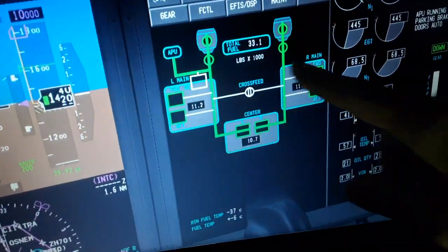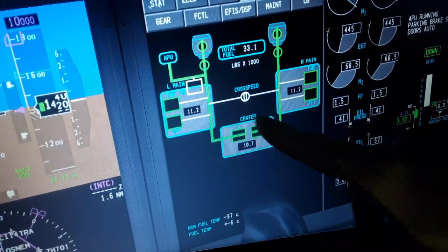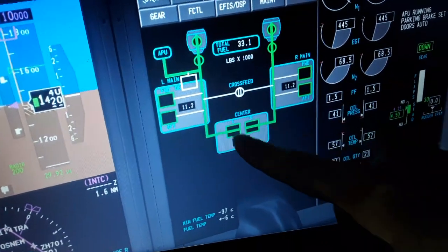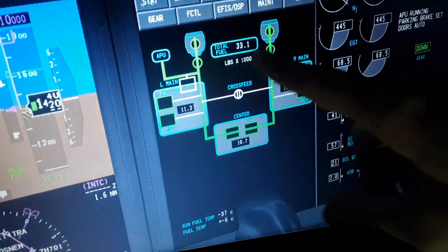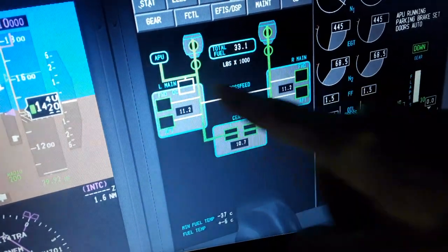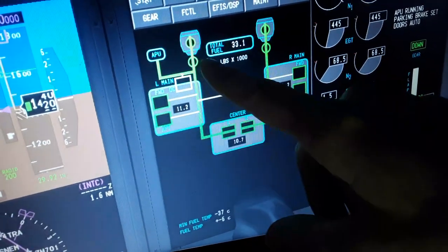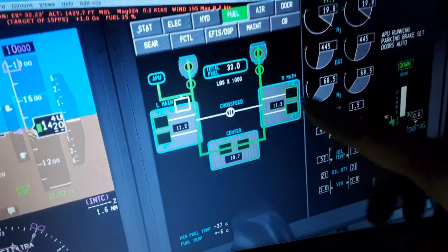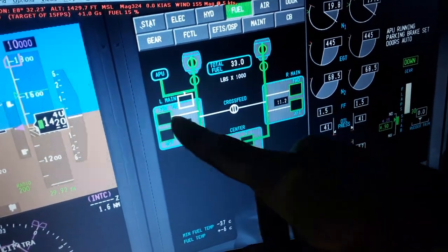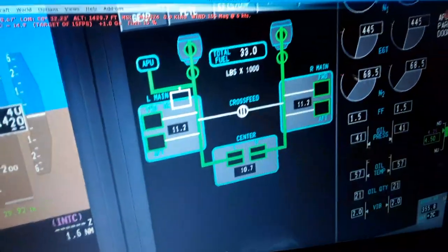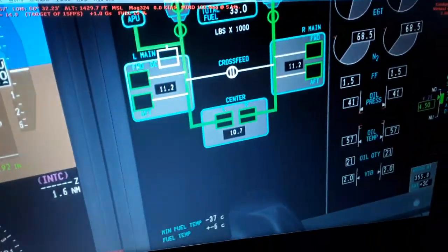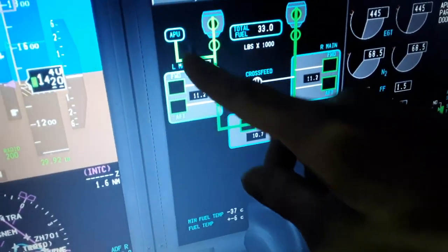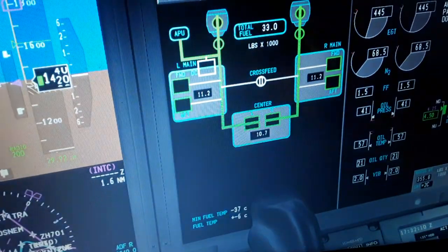We have the transfer of fuel from the left and right wing fuel tank and the center tank into the engine components to heat up the fuel in flight. Also the lubricant and the oil, which turns back to the fuel tanks. This is done automatic from the FADEC. Also we have the low high pressure right now, fuel valve open and feed from the center and the left and right wing. The crossfeed valve is off, but we can turn it on. We can feed either engine with either pump or either tank. The APU is fed from the left wing using the DC motor.